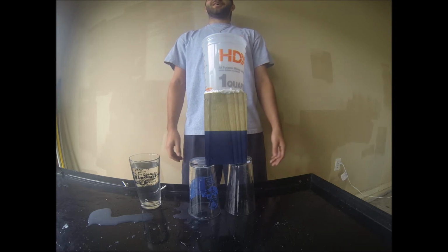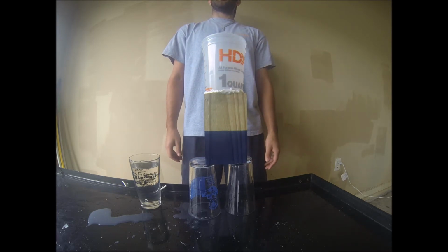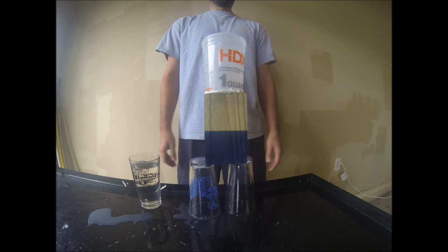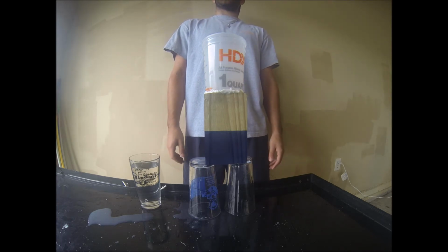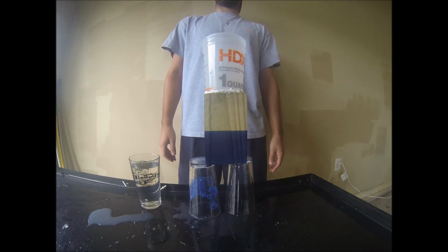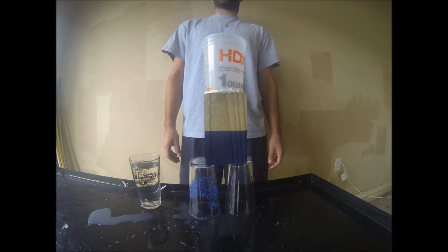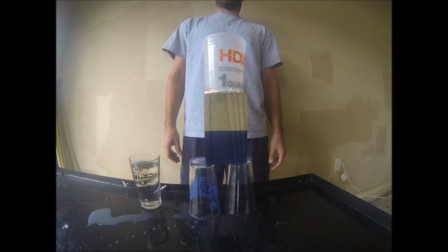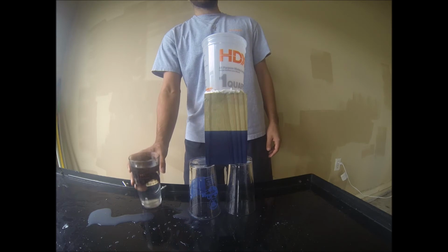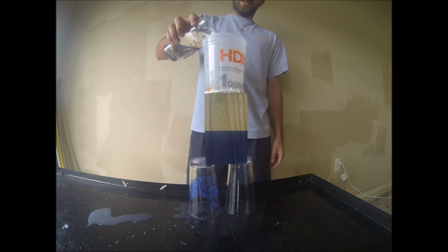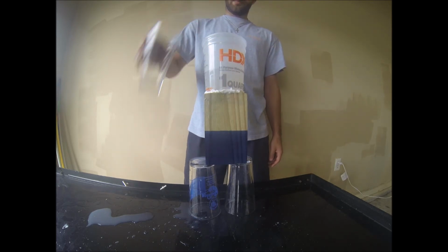Now we will demonstrate series flow through the blocks by pouring water through them. Since the permeability in the blue block is 0, the flow rate in that block is 0. For series flow, the flow rates in each layer are the same. Since the flow rate through the blue block is 0, the flow rate through the entire system is 0. Once poured, we should expect no water to drain through the system. As you can see, no water is draining through the system.